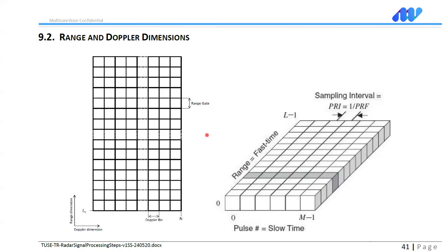Like for cars, you have LRR, long range radar. You have mid range radar. So you can design a multifunctional radar that operates both of them in multiple pulses. It measures the velocity, and then it shifts its parameters to a different radar, and then it acts like a mid-range radar.